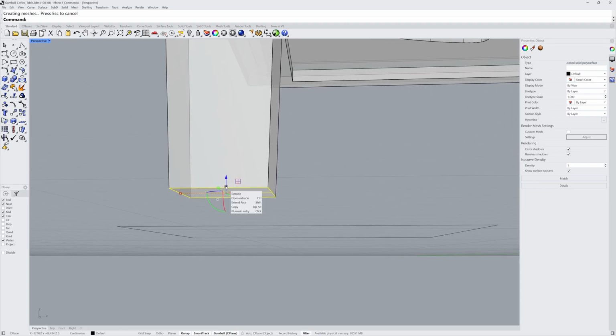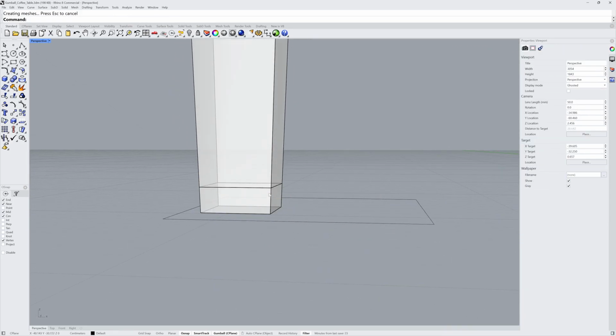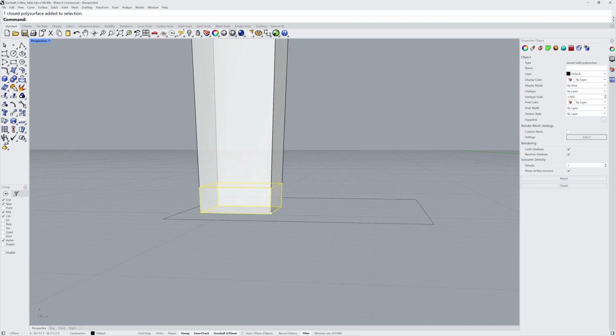Next, I'll use the Extrude handle, and note it has a little circle around the dot. This indicates that that subobject could be extended to match that taper of the adjacent walls. I'll start dragging down, and that'll just be an extrude going straight in the Z direction. If I hold down Shift, it goes in the direction of the angled sides. The last step is to tap the Alt key to make a copy, and then finish the extend with an O-snap along that bottom curve. This creates a separate object, and the foot can now have a separate material as well.